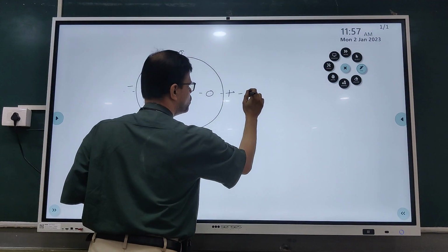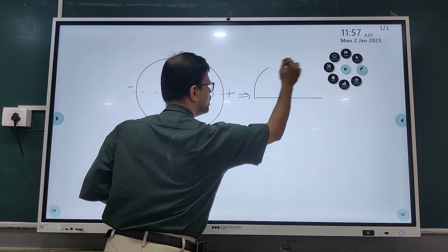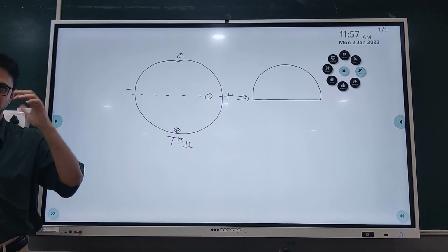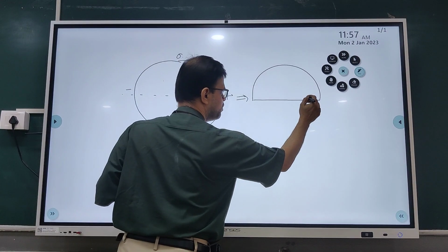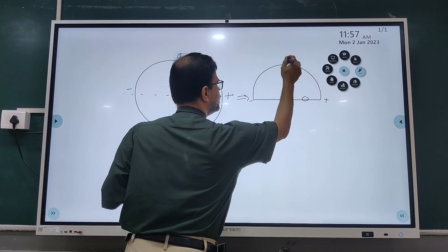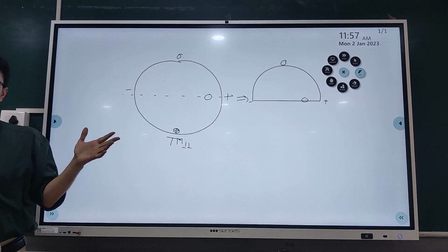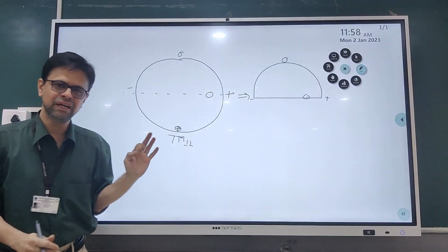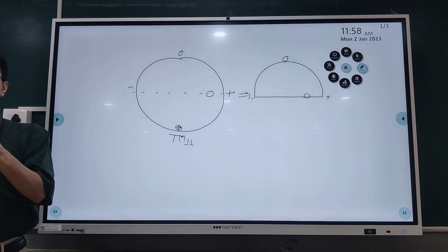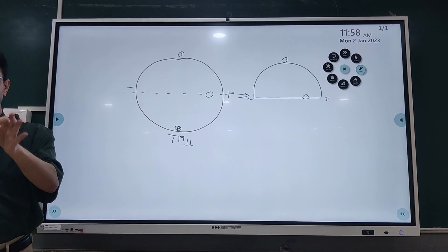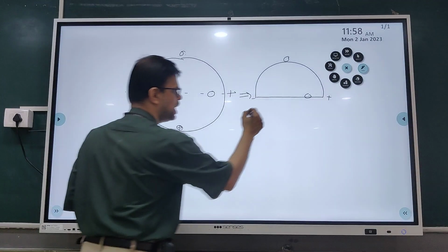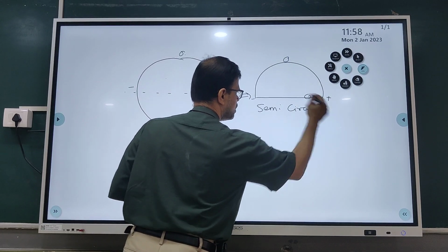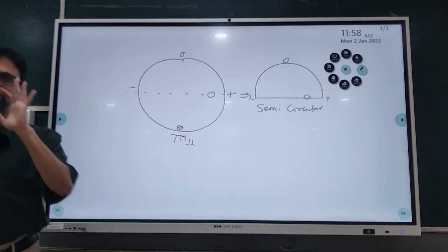So in that process, what I do is realize only half of the circular patch, basically a semicircular microstrip antenna. The field distribution, remember, is not changed. Why? Because only half of this geometry is used. Okay, so this is basically a compact design of the circular microstrip antenna, referred to as the semicircular microstrip antenna. Now why can I do it over here?